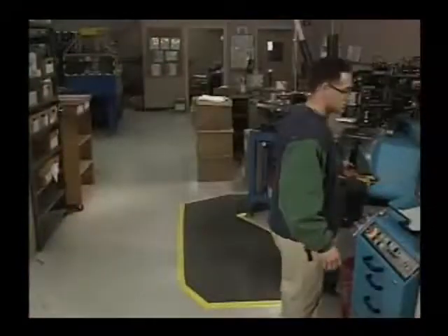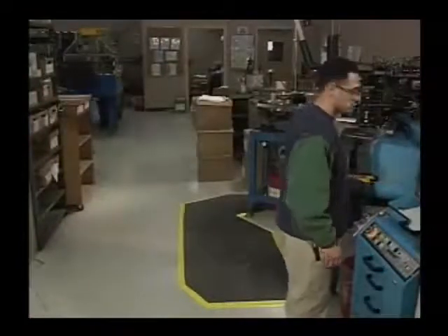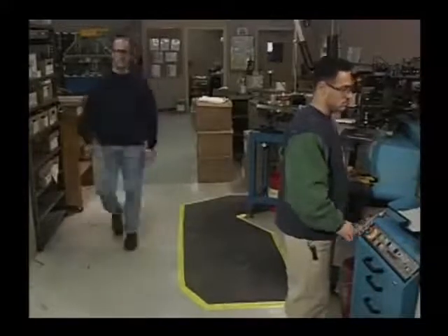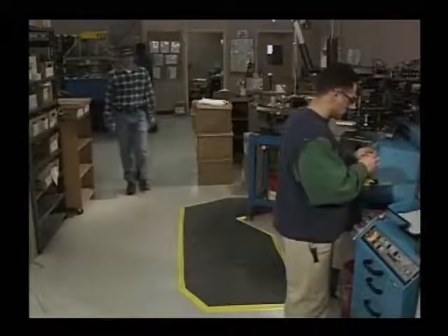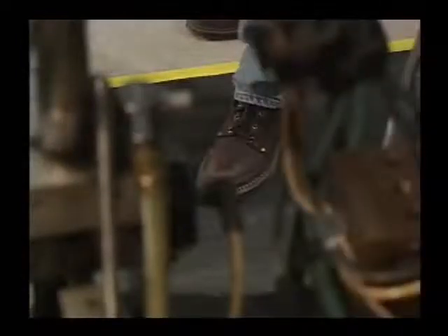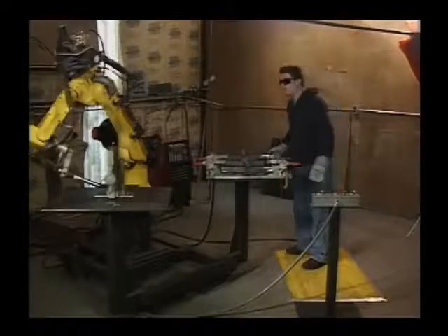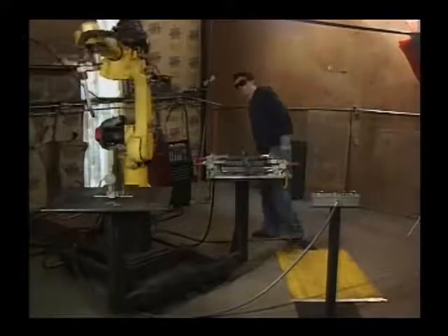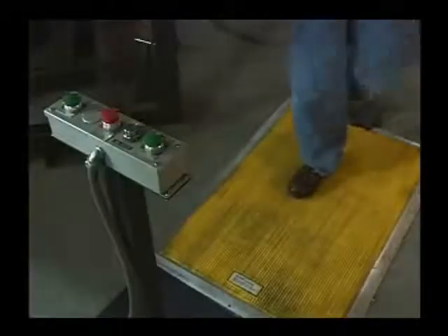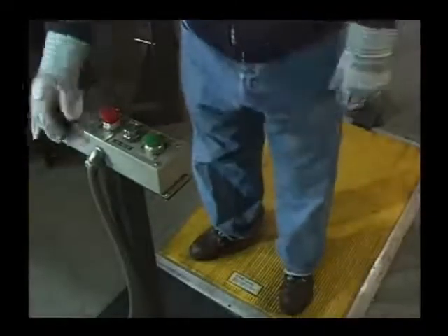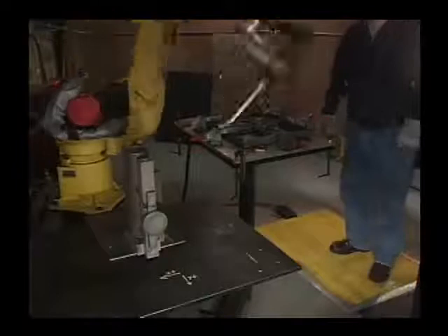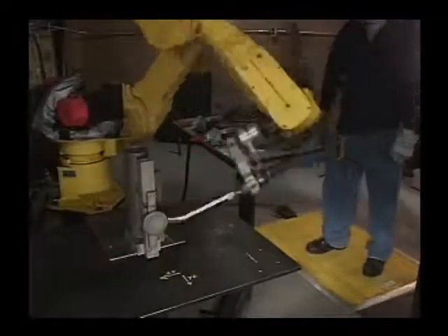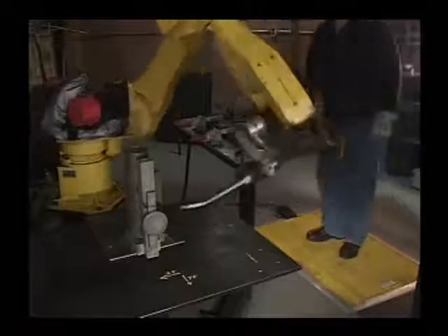Another type of safety device that is frequently used to protect irregularly shaped machine areas is a system of pressure-sensitive mats. These mats have weight-triggered sensors in them. In most cases, when somebody steps on a mat, the relay switch immediately cuts off the power and stops the machine. But pressure-sensitive mats can also be set up to shut down the machine if the operator steps off of them. Used in this way, they protect workers by forcing them to remain in a safe position while they operate the machine.